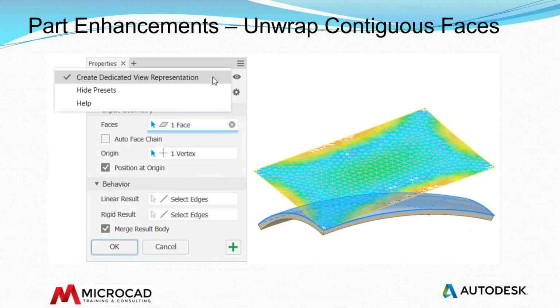The new unwrap command can flatten faces that cannot be calculated with the unfold or sheet metal flat pattern commands. For example, to determine a fabric pattern or a flattening of a stamped object. Unwrap does not use bend calculations to flatten the selected faces. It will display a heat map, and it will show you the areas of highest to least tension. You can specify contiguous segments to remain linear or rigid. The unwrap option creates a dedicated view representation, makes it easier to isolate and to document the output surface.